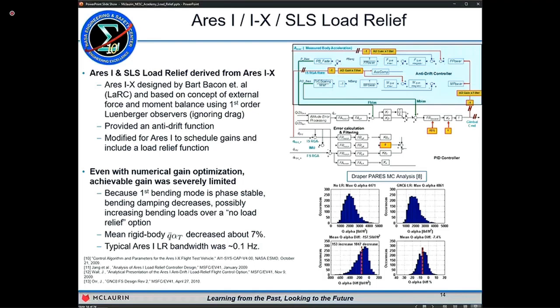running in a high fidelity covariance analysis, and just based on inertial data alone, without winds, we're able to estimate alpha with a 1 sigma covariance of about 1/10 of a degree. This is excellent. And the key there is that by using GPS information to estimate the error statistics in a traditional 21 state EKF navigation Kalman filter, we can take out, or reduce, a lot of the error terms that would corrupt the angle of attack estimates.